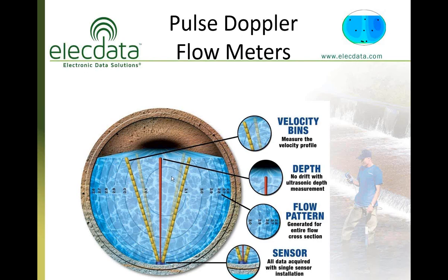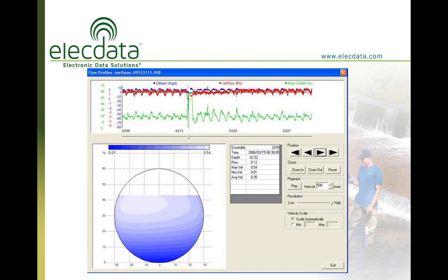So by using these components, we can accurately measure the flow rate in much larger channels, be they round pipes, trapezoidal ditches, rectangular channels, whatever you have. And by doing this, we can get these kinds of pictures where we can actually see that velocity structure, that velocity profile within the pipe as depicted by the graph in the lower left-hand corner.